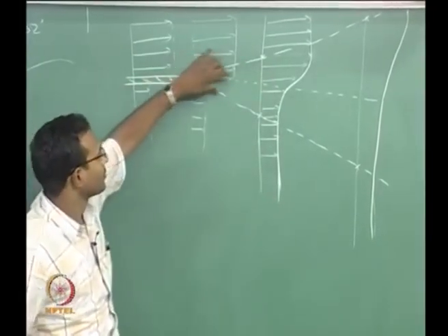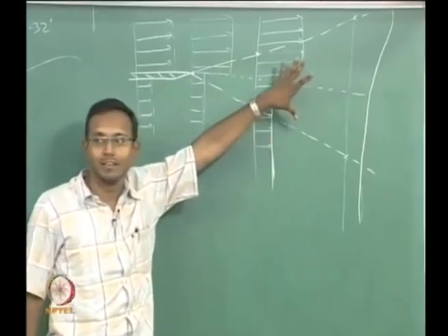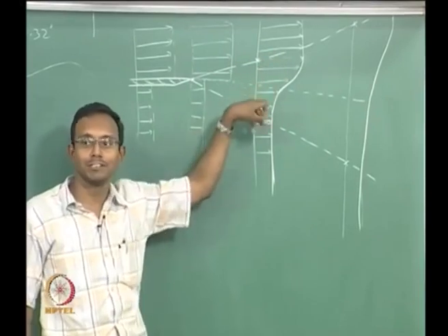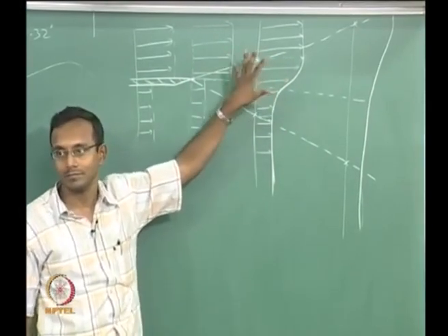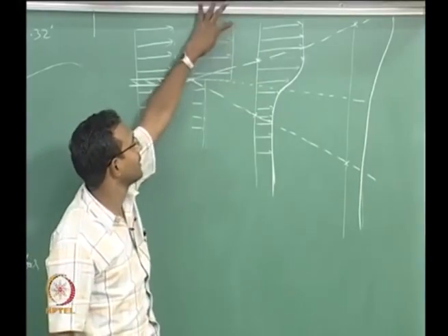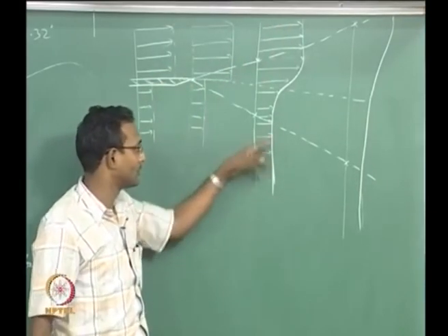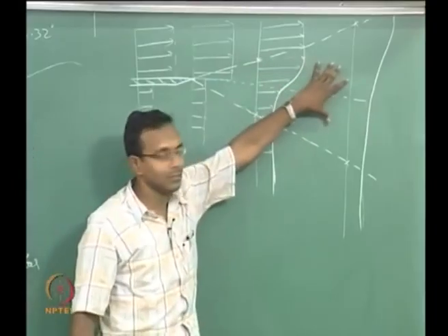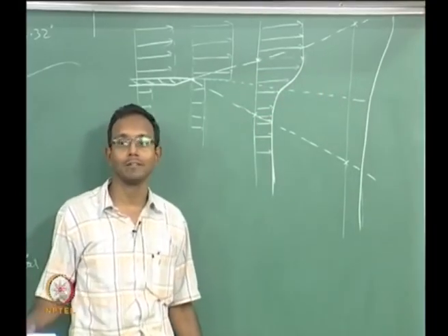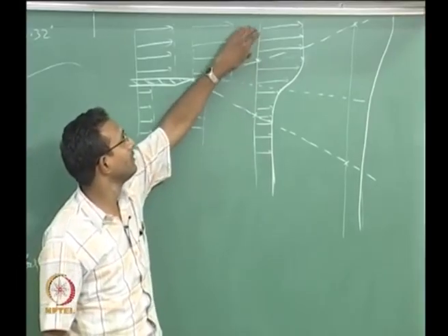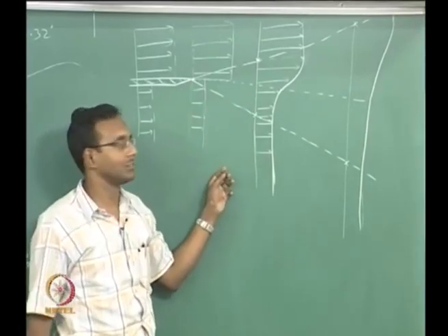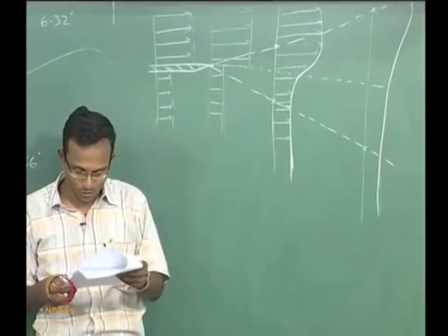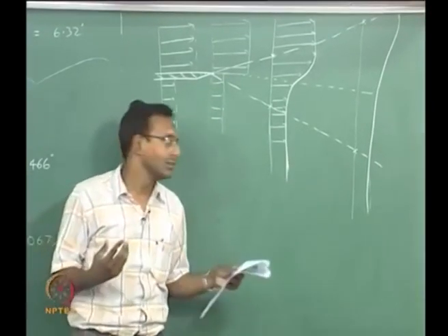This particular region or band of fluid elements I am considering is the only region where viscous diffusion or vorticity redistribution is happening. Outside this I am going to say the velocity gradients are almost 0, same thing below, almost 0 velocity gradients. So, there is no vorticity. This particular region is called the region of shear forces or the shear layer. This layer is in between the two regions where there is not much of viscous forces. So, this in-between region is called the shear layer. And if you do more of a fluid mechanics course, you will start seeing that.